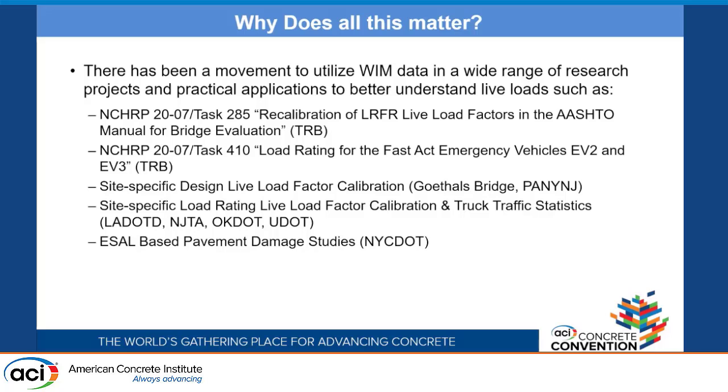And we've done several cases for owners, particularly for long span bridges, where we've developed custom design live loads so that when we're putting $1 billion into a bridge, we want to make sure that that bridge is going to last 75 years or 100 years or more. So we want to make sure the loads we're designing for are the appropriate loads. We don't want to over-design it, and we don't want to under-design it.